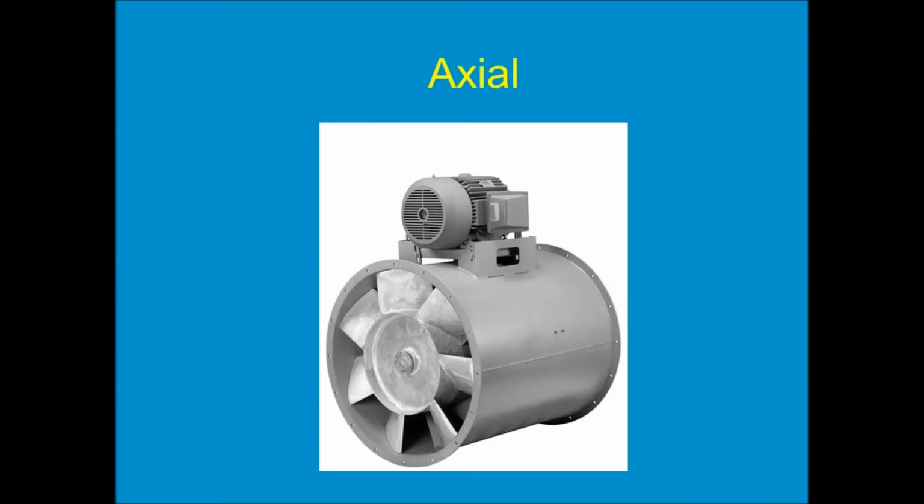However, there is a type of axial impeller, a vane axial and tube axial, where the blades themselves are very short and stubby, and the central hub is a much bigger diameter, and this type of fan shown here can move air against a significant amount of resistance.